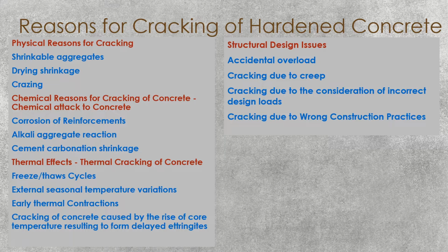If the concrete is porous or there are small cracks that give room for moisture and oxygen to penetrate to the reinforcement, then the reinforcement starts corroding. With the corrosion, the internal volume increases. The rust or corrosive material will expand and the concrete will get cracked, and spalling of the concrete could also occur.